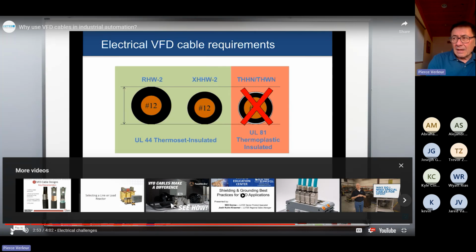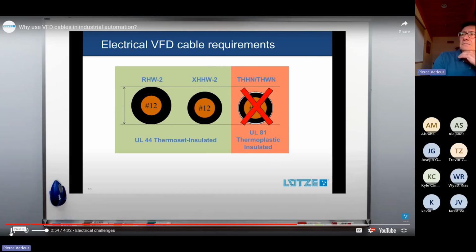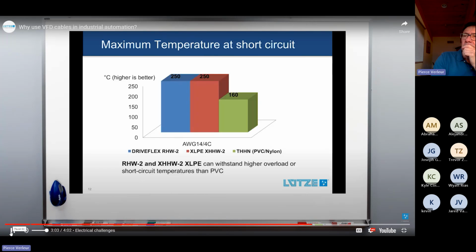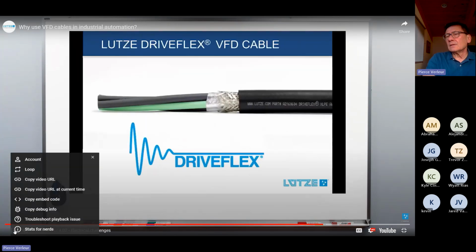of the reasons. The fact is that this cable can help in both of those cases, certainly in the case where that drive is non-compliant to NEMA MG1 and is putting out high voltage spikes to the line for an extended time. PVC insulation is just a bad choice from a voltage standpoint, and that's why we have switched all our VFD cable to XLPE, which is simply a much better insulation and safer for use with VFDs compared to PVC or THHN-based wiring.